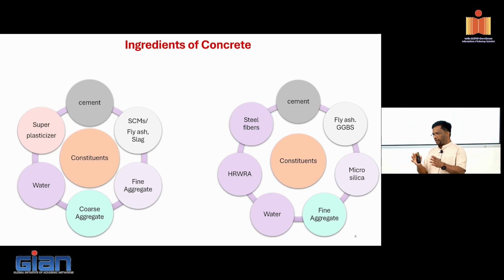If you look at the normal compositions of cement that we use in concrete, you really don't need water to binder ratio more than 0.2. Okay. So, as you said correctly, typically we go for 0.35, 0.4, 0.45 also in regular constructions, because this chemical admixture that we are going to add, superplasticizer, is costly. So, if you want to reduce the cost, the easiest thing is to add more water, right? For complete hydration of cement, actually you don't need really more than 0.2 water to binder ratio.